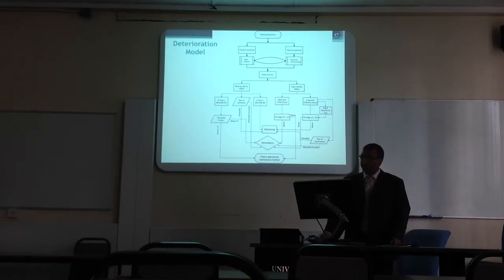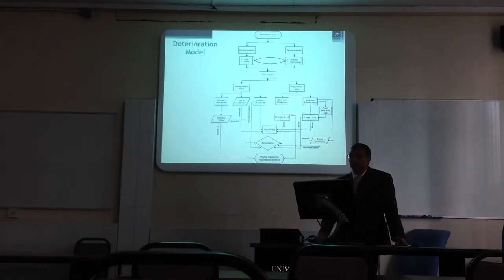For slope stability failure, we have short term, which is total stress, during construction, and long term, which is based on effective stress. That is called embankment, usually taken for long term effective stress, especially for the old embankment and a flooded embankment. So in long term, we take a rapid drawdown case as a long term because the flooding occurs and the failure doesn't occur at that time. It occurs after the water receded from the embankment.